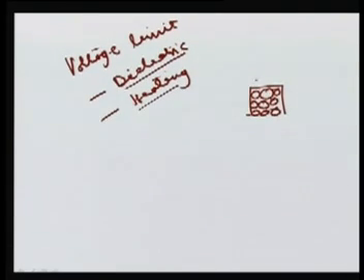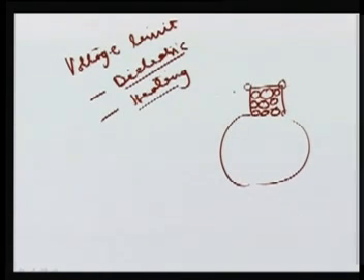So what happens at these corners, we have the excessive field, and therefore more eddy current flowing in this core. This is basically your rotor and stator as well. So there is more eddy current and more loss. If you are going for more voltage, there will be more flux and more stress, and there may be heating, and that is not desirable.